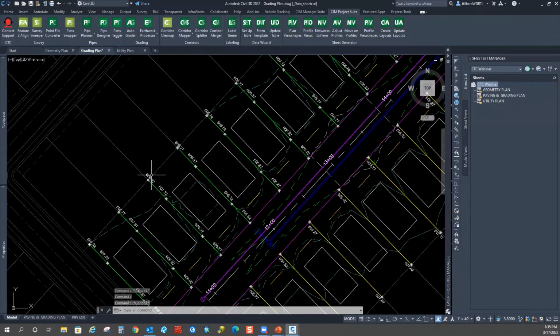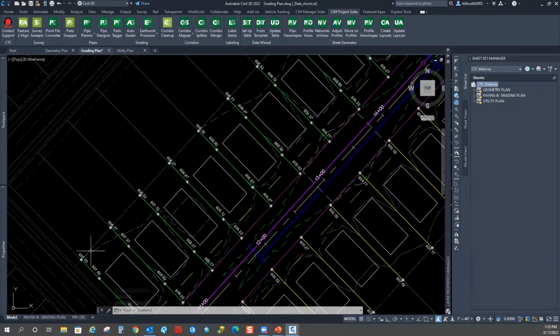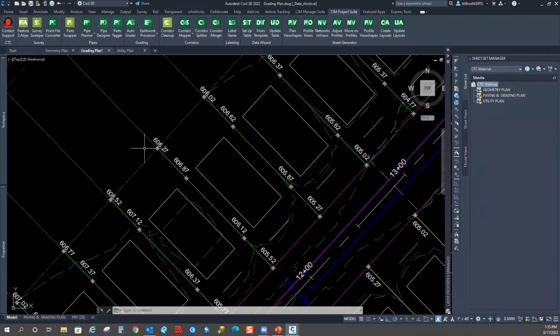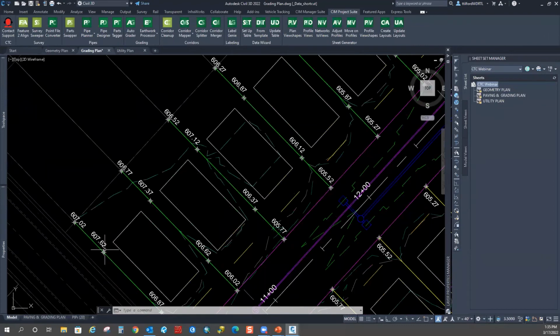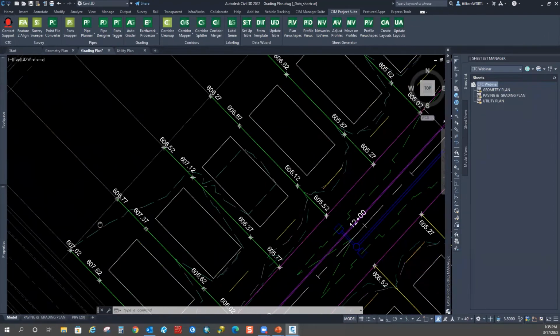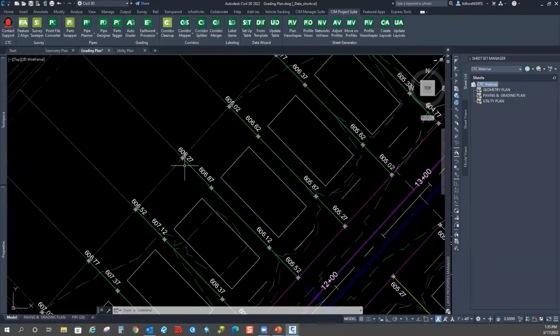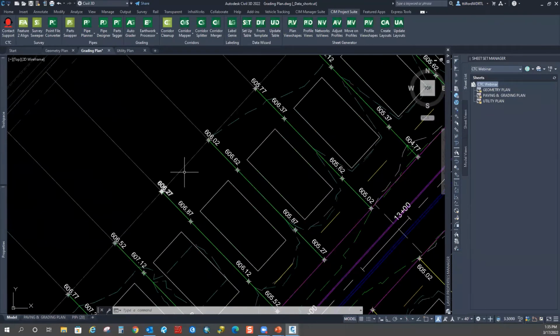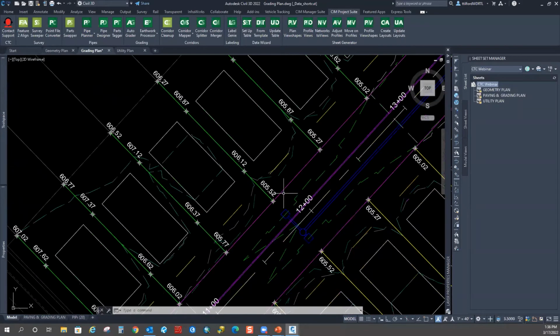This would be higher up. So if this feature line in the back was varying and this was all touching, it would not change the grades. It would come back here, grade up to here, and whatever the difference was, that's what it would be. It would not update these back of lot elevations, because the feature line running back in here is higher in the hierarchy than these children and the front one.